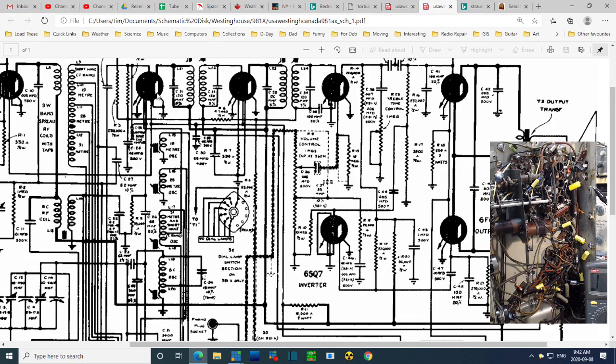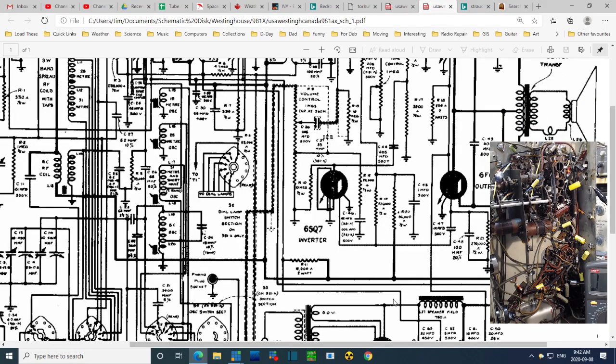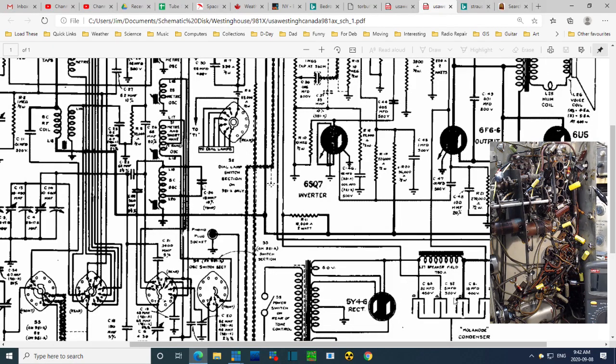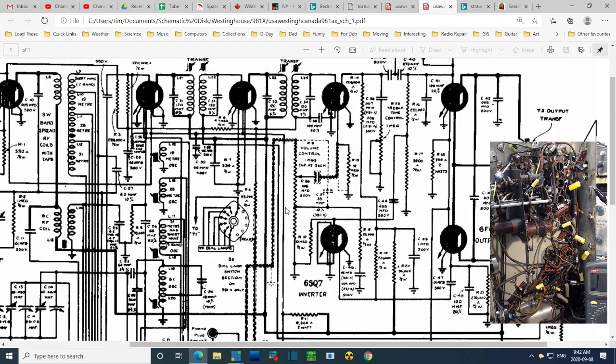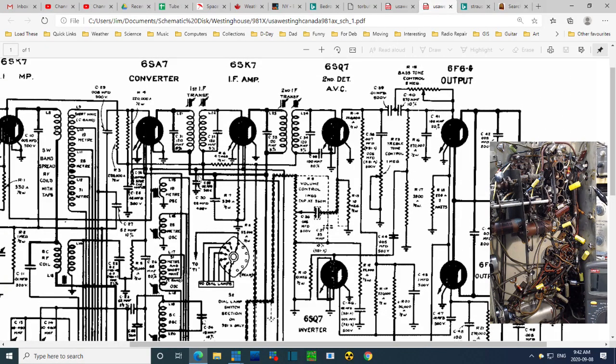It's too bad these tubes are all blacked out here. It's going into each tube, and then it finds its way back to B plus through this resistor. That for sure is a screen line. And what's this? This is probably screen. Oh, another filter on it. Right, filtering capacitor and the resistor, Jim, resistor. My head's getting all mixed up here.